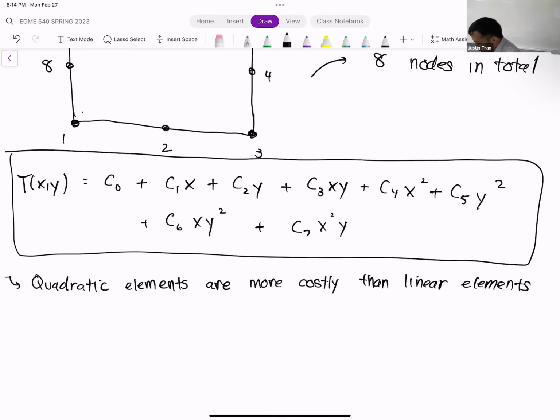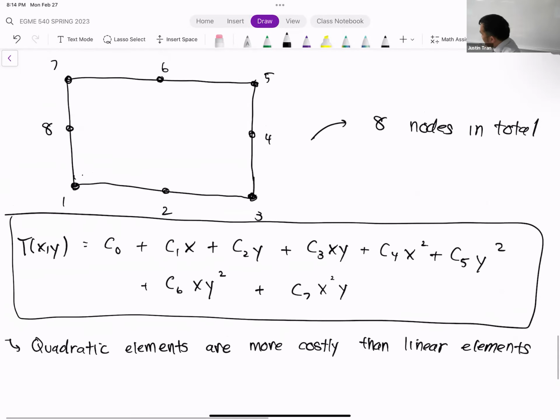And so before we go, I'll leave you with one thought. We've already seen that, just by going from a 3-sided shape, a triangle, to a 4-sided shape, a rectangle, we get a ton of benefits, right? By using a rectangle, our shape functions are much better filled. And a question that I've always had for the longest time is, why stop at 4?